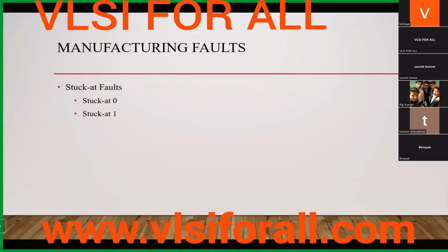Okay, yes. So it's actually during the manufacturing, that's what everyone answered. During the manufacturing of the chip, the process is very complex, so there might be chances that some part of your chip or some circuit gets connected to the power rails. It's either the ground power rail or the VDD or VSS, whatever you wanted to call it, so that we cannot drive that particular signal to anything else.